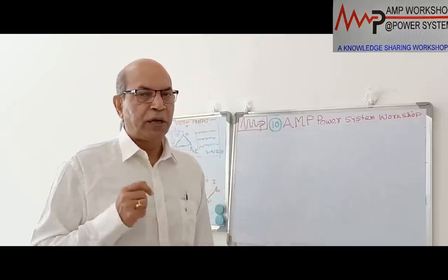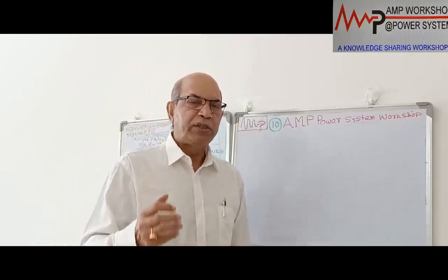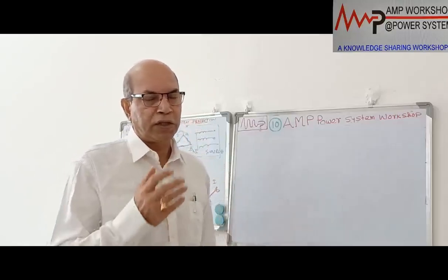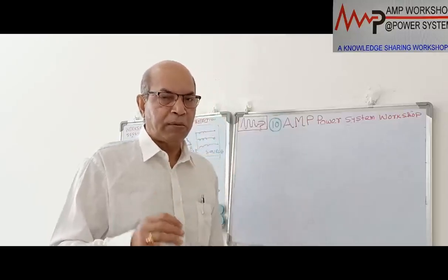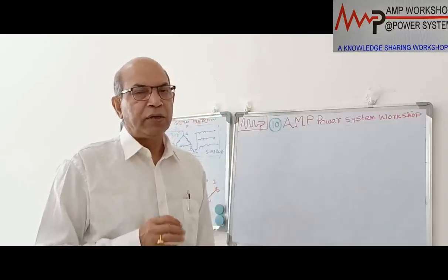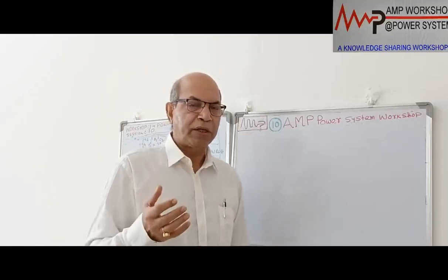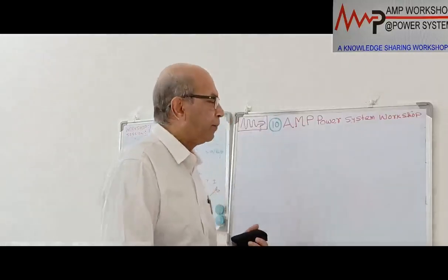But during an earth fault condition, it will draw the earth fault zero sequence current. The zero sequence current will flow through the transformer, and it will give a zero sequence path to the transformer as well as the external earth point. Then, based on the earth fault current, we can provide the earth fault protection to the various outgoing feeders, which I have shown in the previous single line diagram.